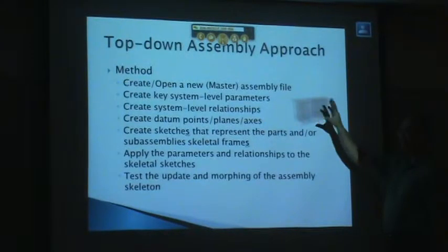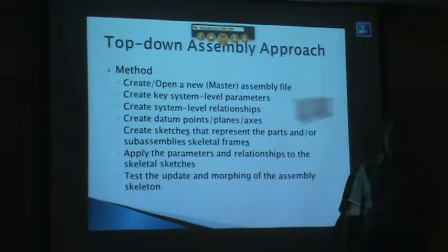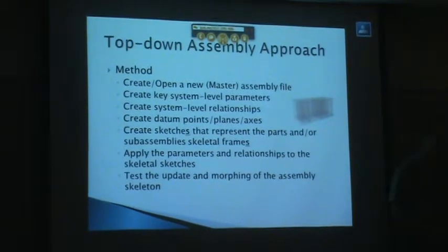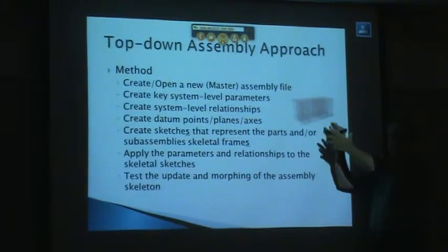After you get this all kind of connected and you think things should behave right, what you do is you test to see if it actually does. You change the length, you change the height, you change the width, and you watch what happens to your skeleton structure. If it doesn't update and it doesn't change in dimension and size, go in and fix it.